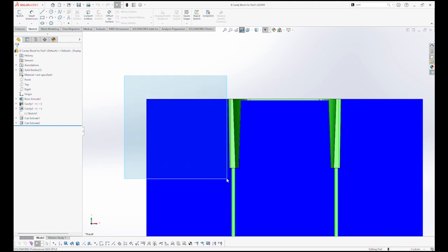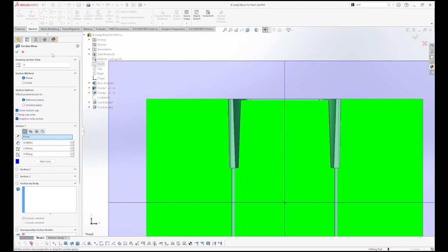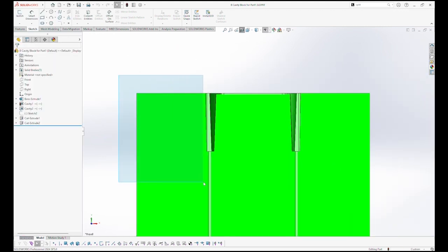And it's a little harder to see with that blue on there. Hold on a second. There we go. So once again, we're going to draw our box, and we're going to see this is the reverse of the modeled part, but you can see the draft on the right edge of that relative to the part there. And then we're going to draw a green box here, and you can see on the left edge compared to the tool geometry that we have draft on the core.